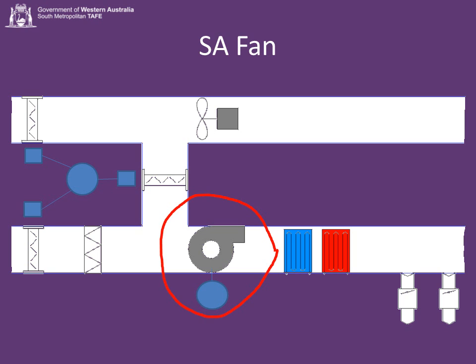If we don't do this, then there's going to be too much velocity at the VAVs and they'll whistle. Also, we stand a very good chance of overpressurizing the ducts. So we need to moderate the supply air fan, or the supply air fan flow.